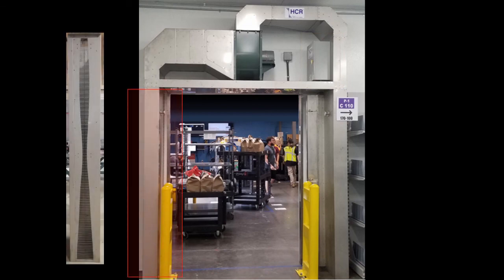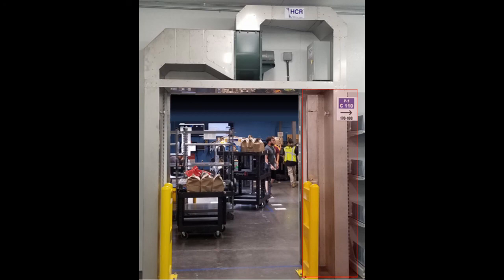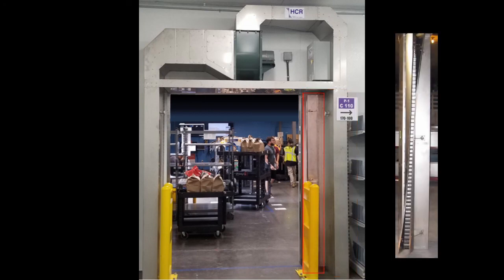A screen exists here that needs to be kept free of debris, else air may be restricted. The discharge plenum is where air is blown across the doorway. The nozzle pictured here directs the air in order to match the momentum of the flow through the doorway. You'll learn how to adjust this shape in future videos.